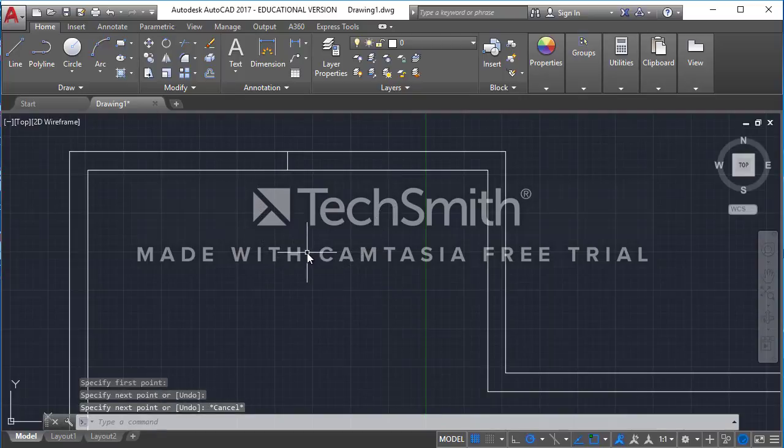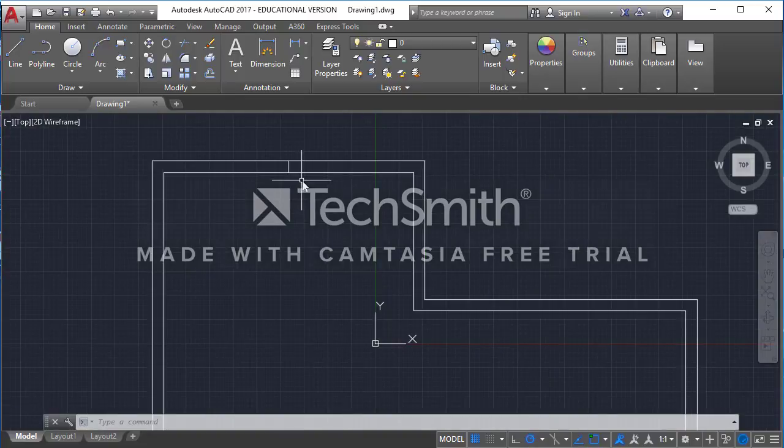Well, for those of you that have worked in construction a little bit, most doors are going to be 3 feet wide, okay? A 3-foot wide door is the typical ADA accessible door. All of these doors are probably all 3 feet. That's probably maybe even a little bit bigger because that might be like a closet. Some of these double doors are going to be 6 feet, but most doors are going to be 3 feet. Some of your restroom doors or closet doors at home might be 2'6", okay? But again, for simplicity, we're going to go ahead and say all doors are 3 feet.